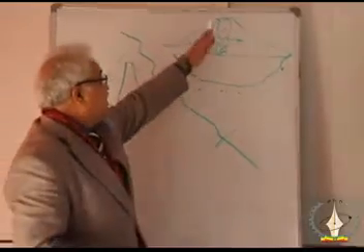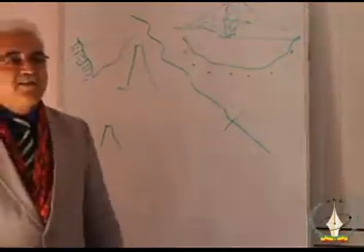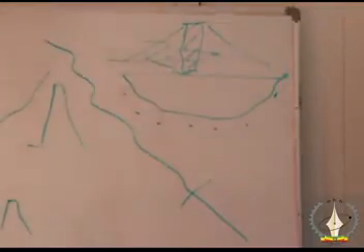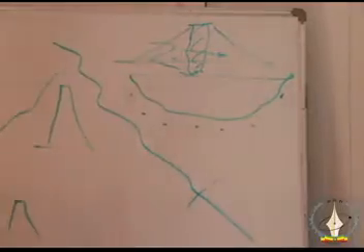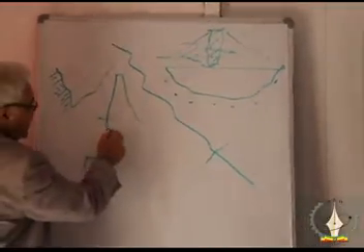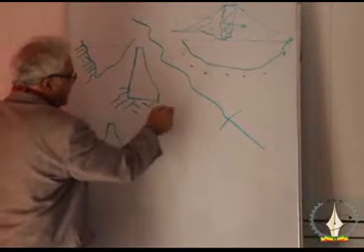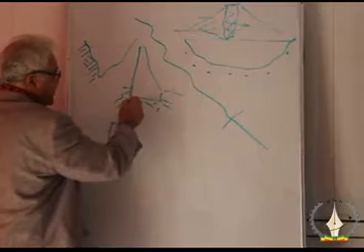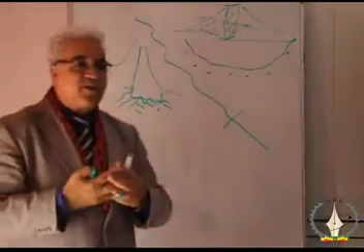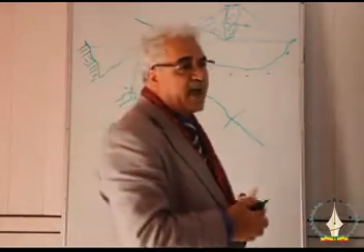But if this is a concrete dam up to here, and then the water is going underneath it, that will be very dangerous for the stability of the concrete structure. While in this case, if this is a concrete dam and these are rocks, then they will design it in such a way that the bond between the concrete and rock is perfect and nothing happens.